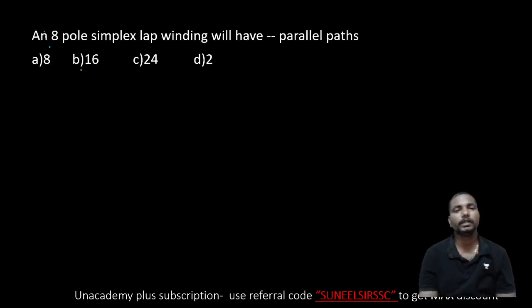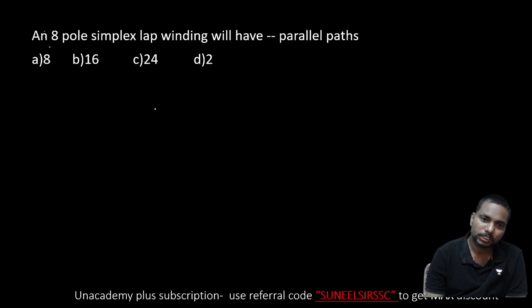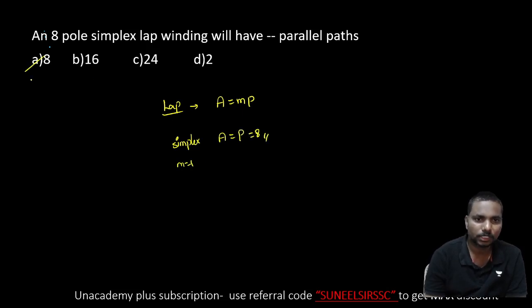And coming to the next one, an 8-pole simplex lap winding will have dash parallel paths. So just now I have given, in case of lap winding, what is the formula? A is equal to MP. They have given simplex. So simplex in the sense M is equal to 1. A is equal to P, that is equal to 8. So the answer is option A.